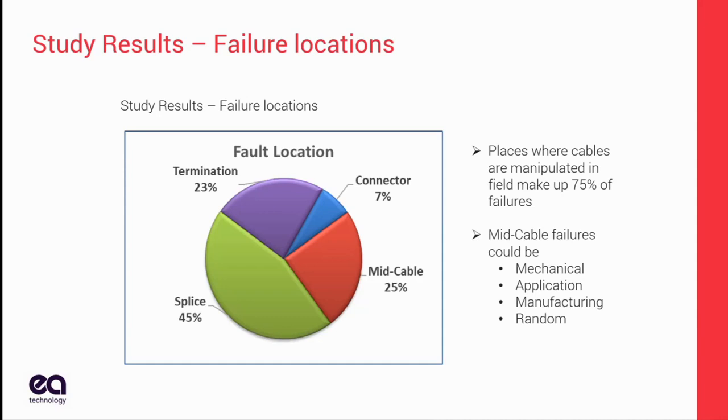Mid cable, as it comes out of the factory, is impacted by some of the environment around it. Sometimes rocks in buried cable will migrate up and press in on the insulation, causing a failure. Or with undersea cable, you could have a water problem. But for the most part, in 75% of cases, the fault location was where someone was touching the cable out in the field.